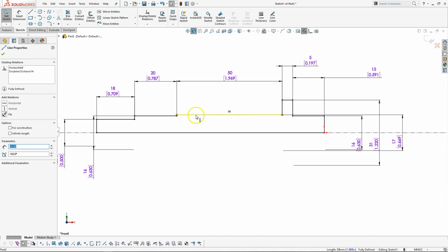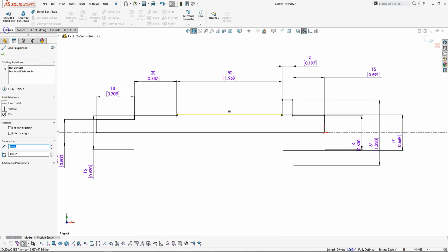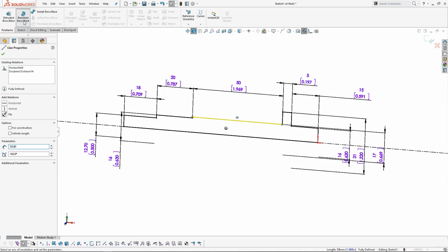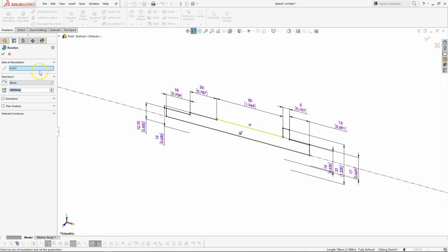I could almost put a little relief in there and say, just in this area. But with the machining processes and the potential for taper hanging out, what are we at? 2, 3, almost 4 inches. Keeping that on line, I may want to put a center in there as well, so that we can support it while we're turning the geometry.